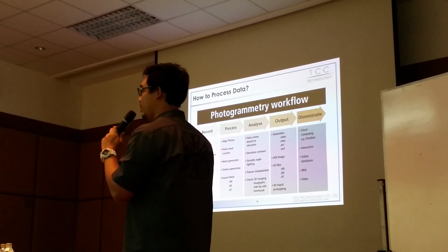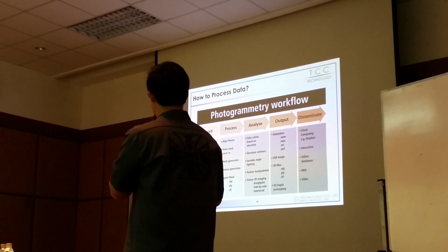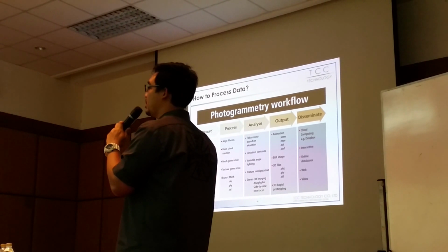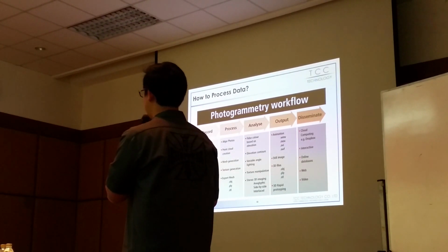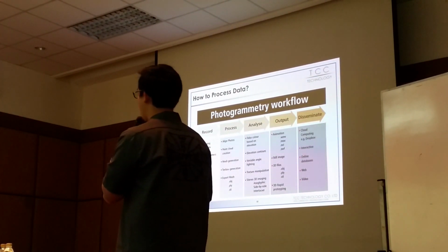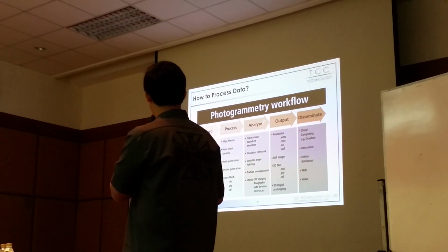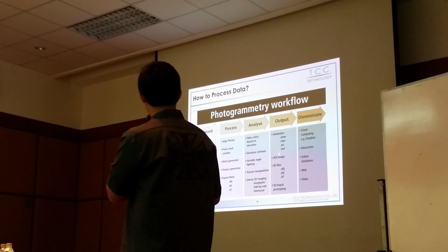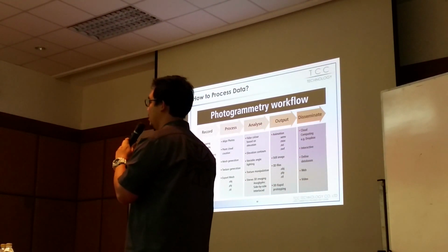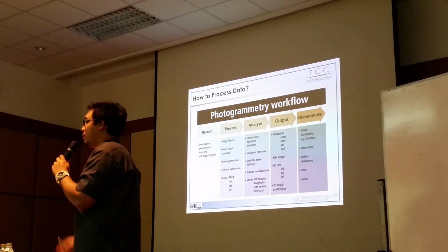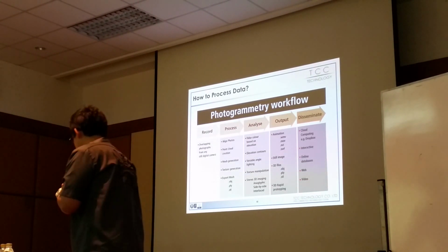Then we extract points from those images and create the point cloud. Then mesh generation produces the digital surface model, and texture generation produces the orthophoto. Then the other option is to analyze, to create the output that we want and use it in other applications. Do you have any questions? No? Really clear?